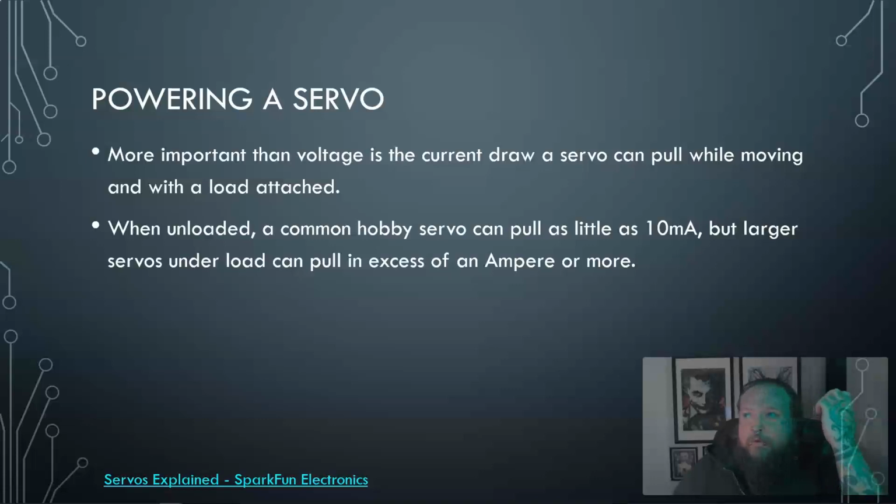So if we brought in things like an ultrasonic sensor and then worked with, say, one servo, well then, remember it was roughly 50 milliamps for that ultrasonic, not 15 amps, and then 10 milliamps for this one servo. So there you've already got 25 milliamps, and that starts adding up as you're doing more work, let alone what's required by the Arduino device itself and anything else that you have hooked up. So it starts adding up.